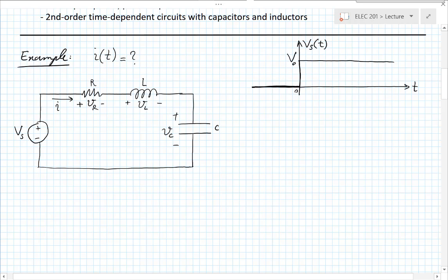OK, so let's write this down together now. First of all, like I said, we have one KVL here. And that's simply, again, the way I'm used to writing things, which for me is usually clockwise. And if I encounter the negative sign of an element first, I'll add a negative here. Then plus VR plus VL plus VC equals 0.